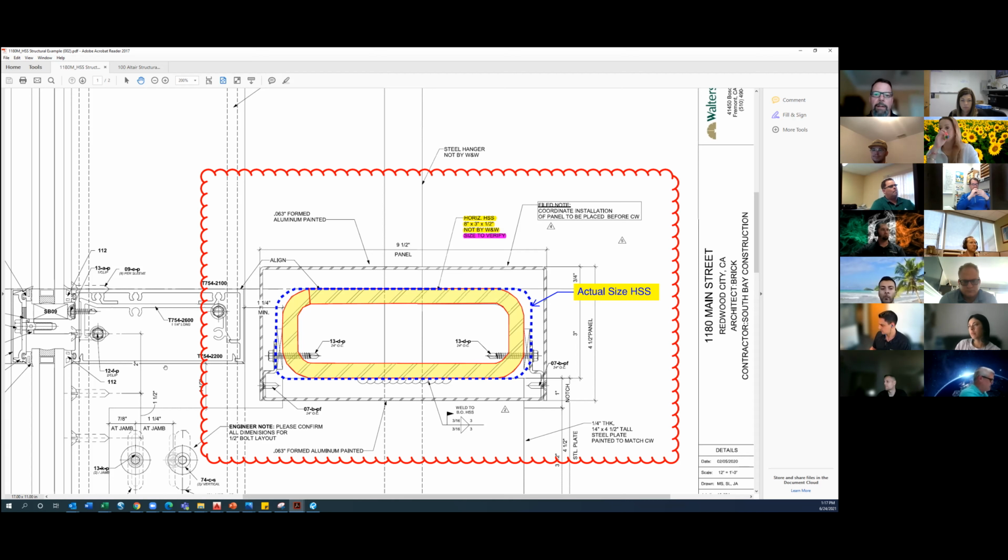That note I highlighted in pink there, size to verify, really kind of killed us. We were saying, hey, why did you guys install a 9x3 when we clearly have an 8x3? And their question is, well, hey, you have size to verify, right? So I went back to the structural drawings, and on the floor plans it clearly shows that tube as a 9x3. I dashed in the actual size of the tube, and I would have had to cut down every single one of those bottom panels to make this work. Thank God they deleted that whole scope, so we didn't have to do any of that work, but it could have been a bit of a mess, and there was quite a bit of that cladding to do. That would not have been fun.